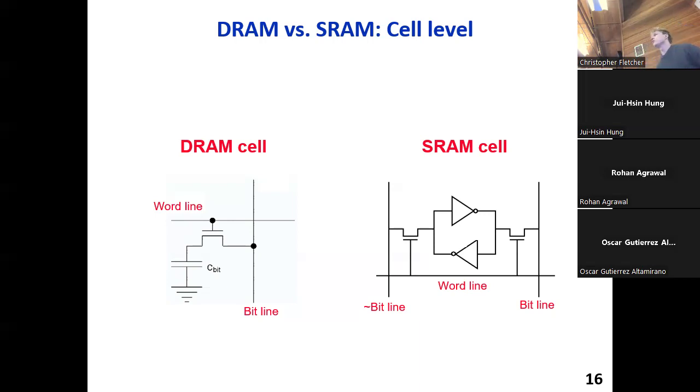Precharge. By having bit line and bit line complement, we're either going to push onto the bit lines a 0 and a 1 or a 1 and a 0. The sense amps are going to sense the difference between these two. Whenever we activate the word line again, we apply fresh charge, in either the 0 or 1 configuration if we're storing a 0 logically, or a 1 followed by a 0 if we're storing a 1 logically. And we no longer need to pre-charge the bit lines.